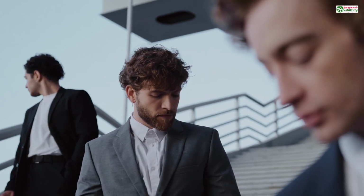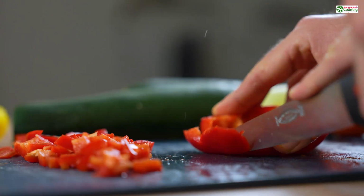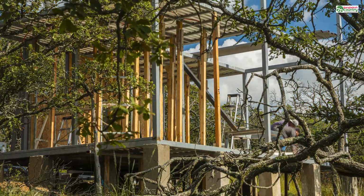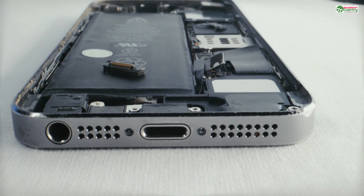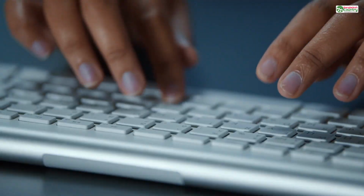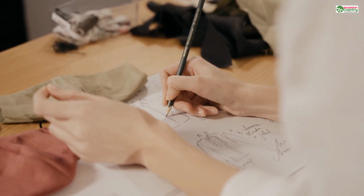This leads to the second crucial habit: model to real-world scale from the very beginning. Don't just eyeball it. Don't just sculpt something that looks about right on your screen and assume you can just scale it later. That's a recipe for disaster. You wouldn't build a house without a blueprint, and you shouldn't build a 3D model without a sense of its final physical dimensions. If you're designing a custom phone case, get a real phone and a set of digital calipers. Measure its exact length, width, and thickness in millimeters. Input those dimensions into your software. Create a simple block of that exact size to serve as your guide. Now build your case around it.